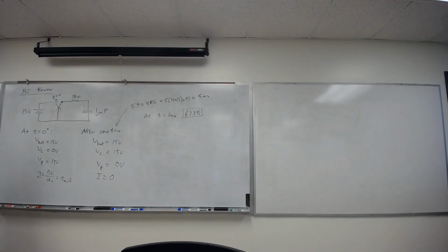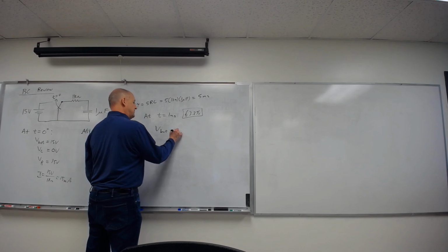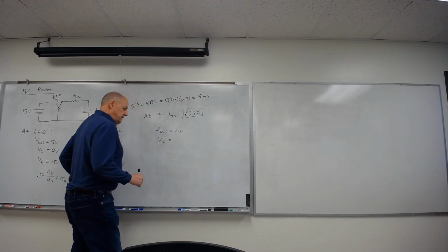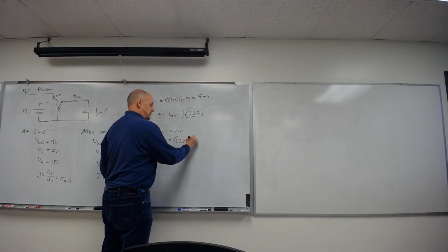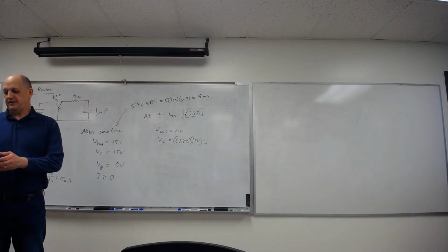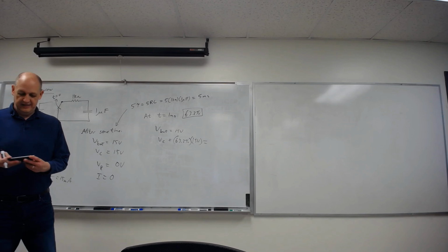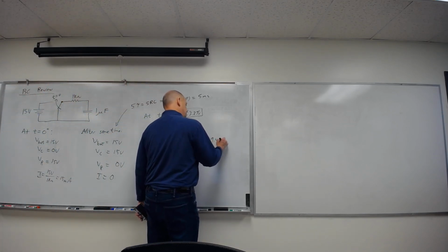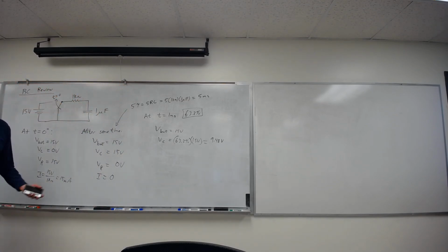All right, so let's try this. After this, the battery voltage is, of course, 15 volts. The capacitor voltage is 63.2% times 15 volts, which is whatever that is. So 0.632 times 15 is 9.48 volts. So after 1 millisecond, we're almost 2/3 of the way there.